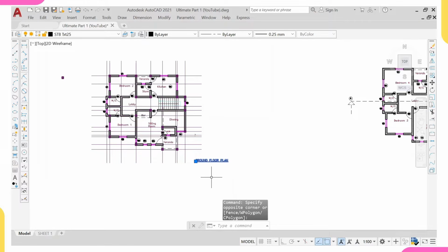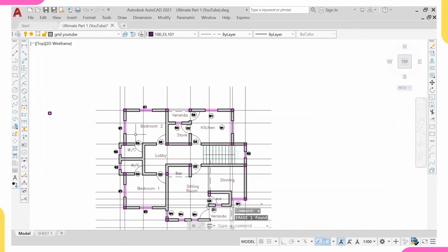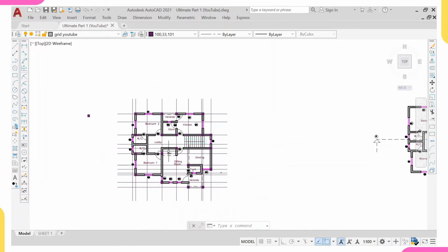So I'll click on this and delete this. It's not necessary, I don't want it. Let's continue. Paneling should not be more than 30 meters square. If your panel is more than 30 meters square, what you do is either increase the depth from 150 to 175, or you break that panel with a beam. Don't worry, let's continue. I will show you the example.